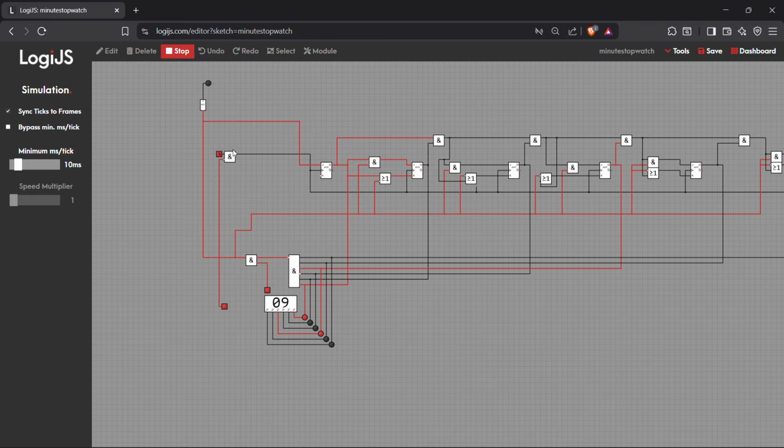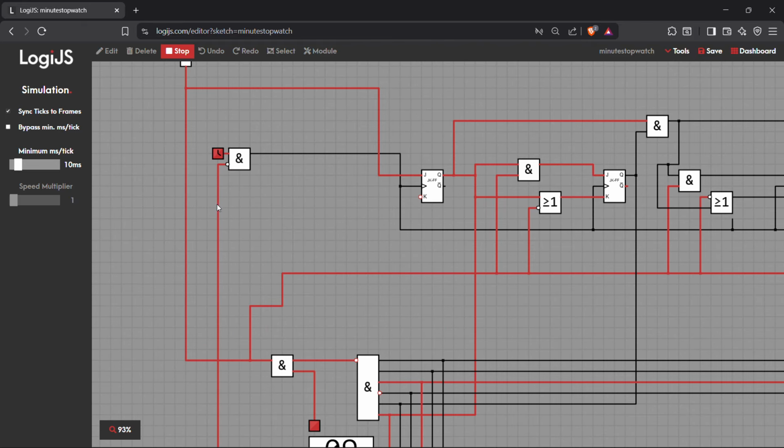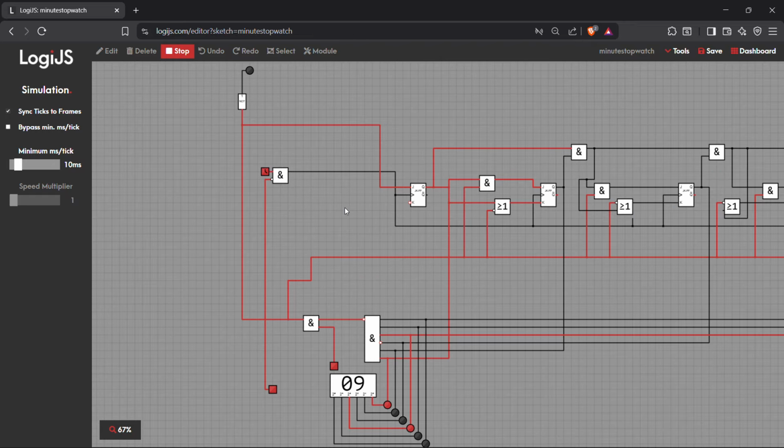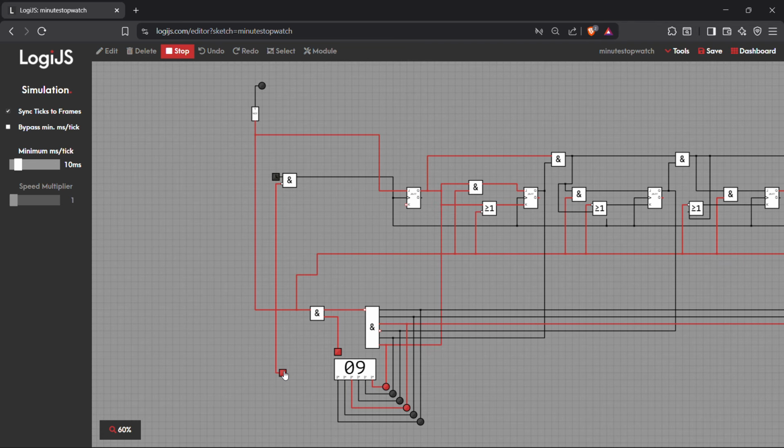Since the pause button is ANDed with the clock signal, the clock will not be passed on, since the AND has a bubble and the pause signal will be inserted as 0 into the AND. So a 0 in AND will result in the output being 0, so the clock will not be passed and the flip-flops will remain at a constant state, that is they will be disabled and not function. After we remove the pause signal, the clock will be transmitted as usual and the timer will continue as it should.